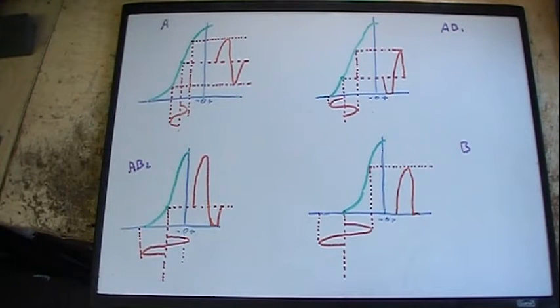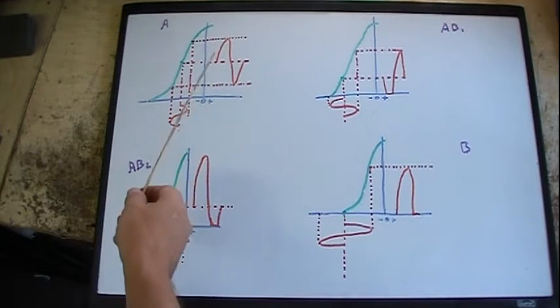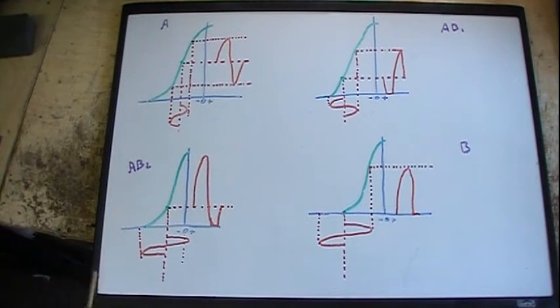Most of the amplifiers you run into, especially in receivers, whether they're push-pull or not, if they're single-ended definitely, but even if they're push-pull, the vast majority, close to 80%, will be Class A. Now there's a reason for that, and I'll get to it in a minute. One thing about Class A, the tube works all the time, so it's the least efficient of amplifiers because the tube's always drawing current. It's always turned on. So that makes it the least efficient.